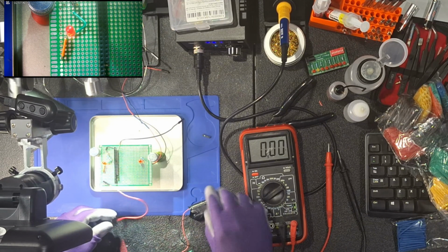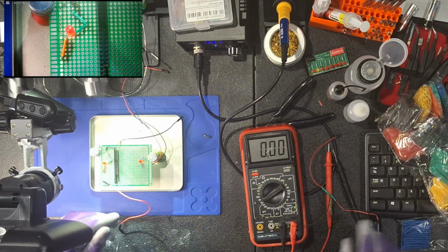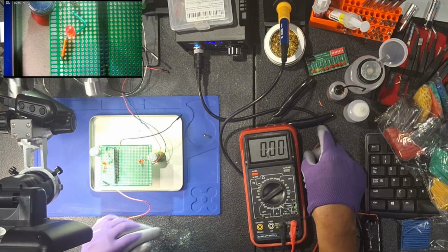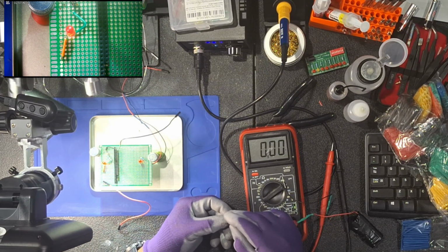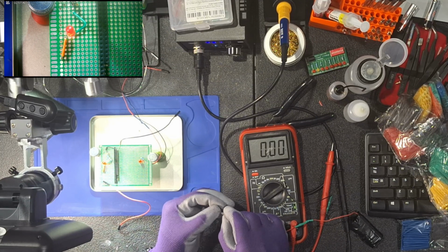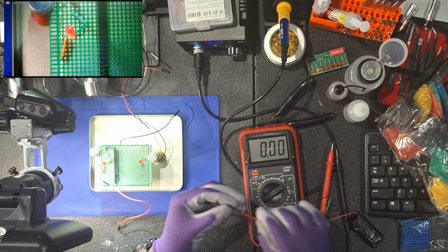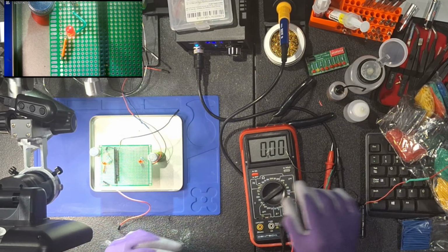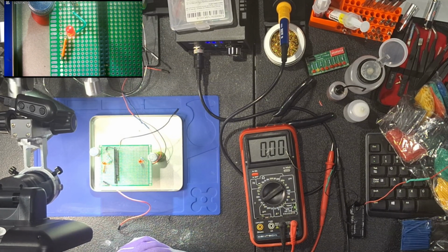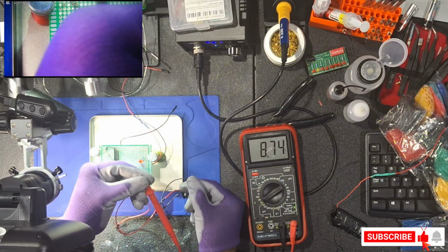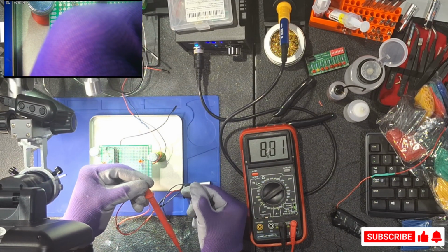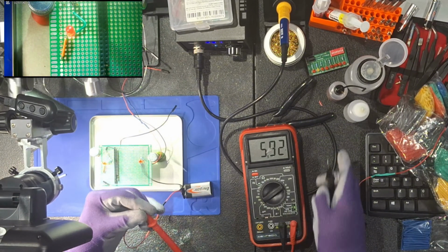Now I'm going to connect the 9 volt with the same LED and see what happens. Well, I did demonstrate this earlier in the intro of the video. 9 volts, the LED needs 2 volts. So it's going to get like 7 additional volts to the LED and eventually it's just going to fry. Alright, I just tested the 9 volt battery. I got 8 volts on it.